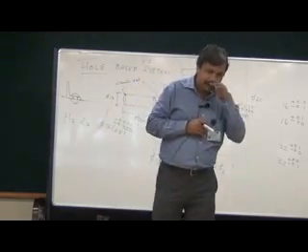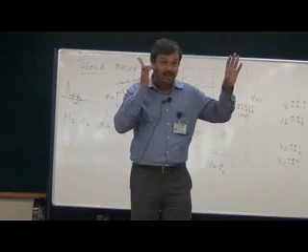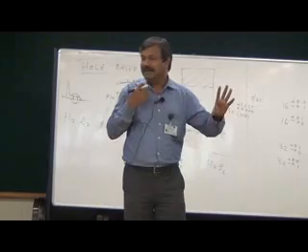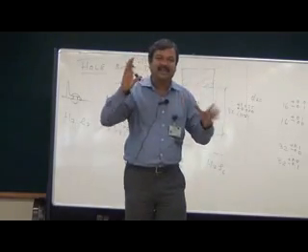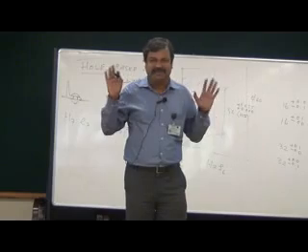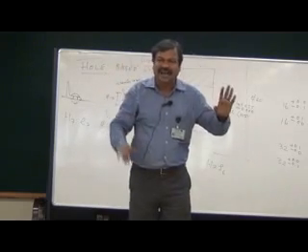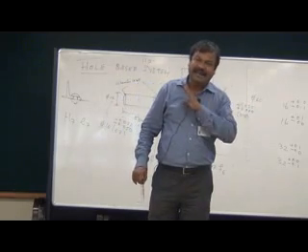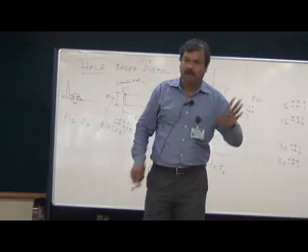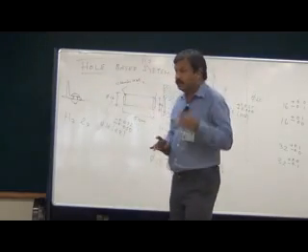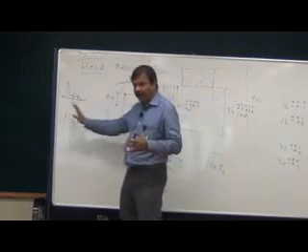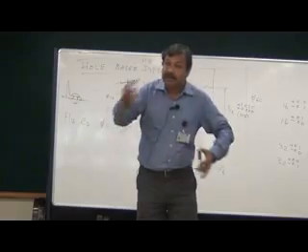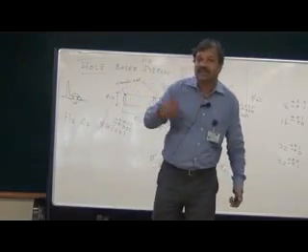Are you able to understand or not? You freeze the tolerance band on the hole. It is always H7 or H6 or H8. These are the only three variations possible. No other ABCD. The hole will always have H. So in 99.99 cases, you will be using only hole based systems. The tolerance of the hole is frozen. Then how will you get the required fit? By changing the tolerance of the shaft.